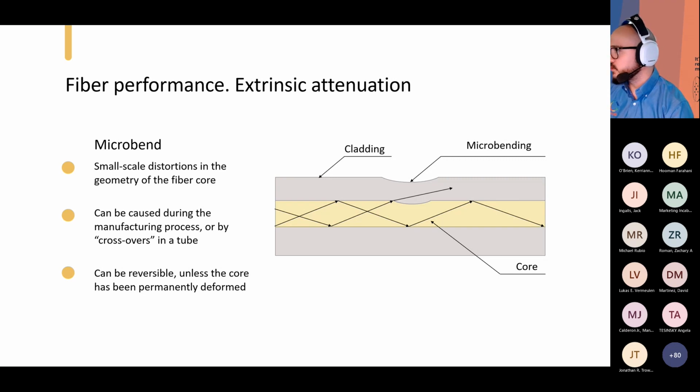Which one can occur due to wrong installation? I'm sure that's related to microbend or macrobend. Both can happen in installation, but I would say you would more commonly see macrobending being an issue during installation.